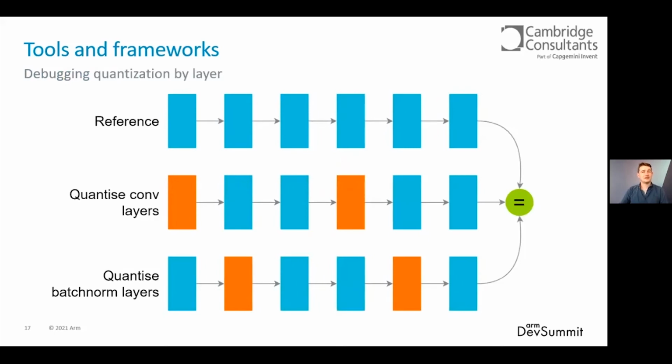A second technique is useful in tracking down inaccuracies when using quantized models. And again, there is limited visibility inside the hardware. By selectively quantizing only some layers and running the network, the reduction on the network's accuracy can be found. Changing which layers are quantized and which are not gives an indication of which are the most sensitive to quantization.